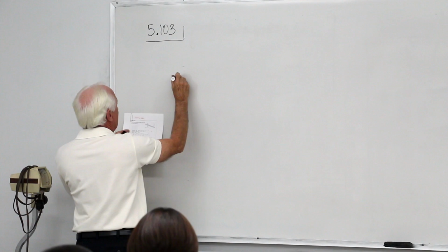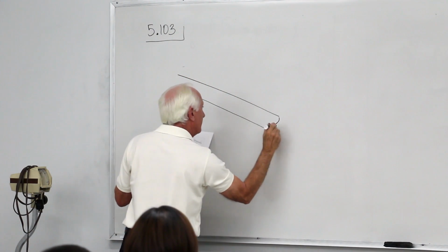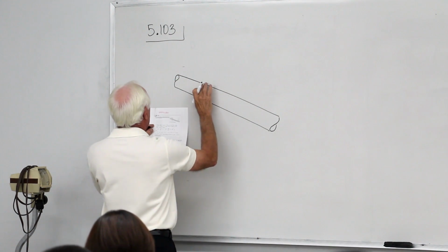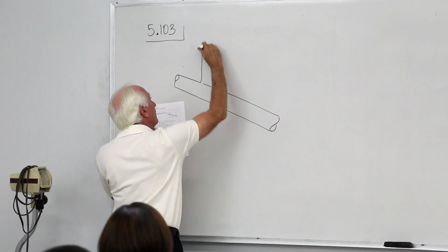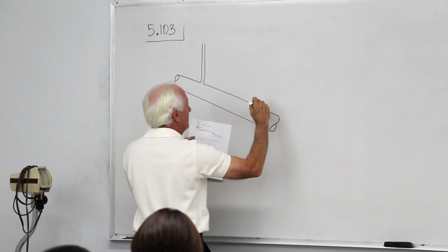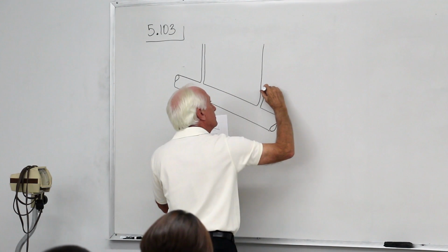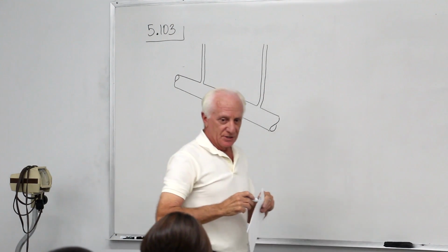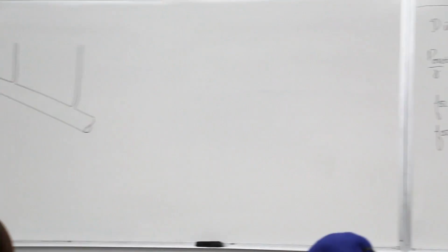All right, here's an inclined pipe. Go right here and here. There's a manometer here. It's a piezometric tube. Comes out and goes up. There's a piezometric tube here. Goes out, goes up. It's a clear tube. This is a review of chapter 2. We use piezometric tubes to measure static pressure, if we can. Sometimes you can't do it, but if you can.